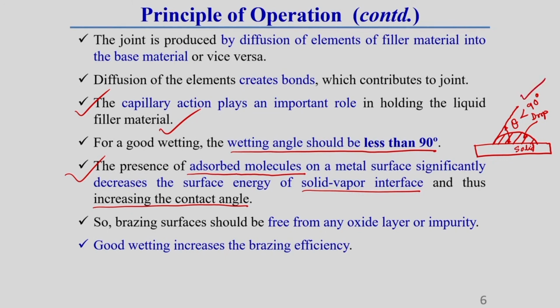That is why you should keep it in mind when you go for joining any surface by the brazing process, that surface should be clean enough. That means there should not be any adsorbed molecules. Adsorbed molecules means things like oxide or grease, or third-party particles, that should not be there. That is why I have written this point.